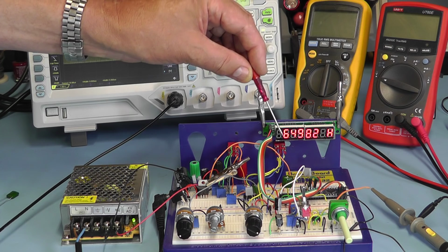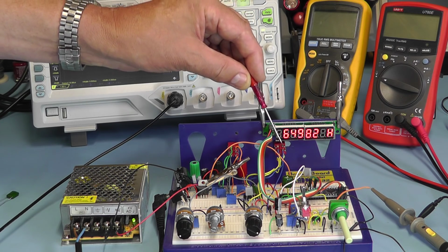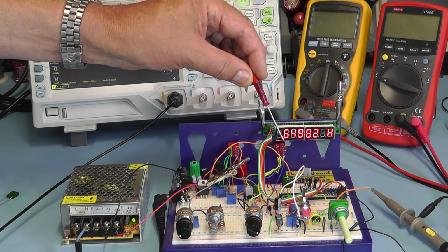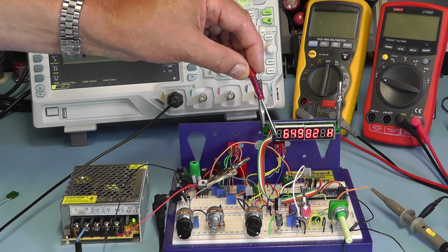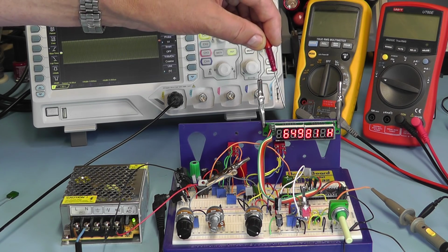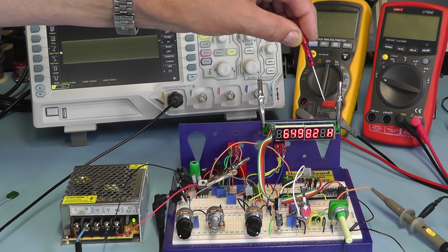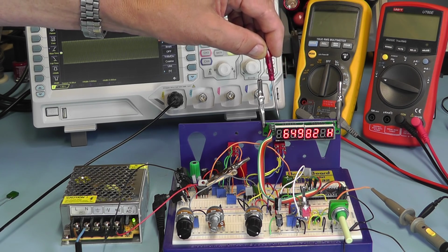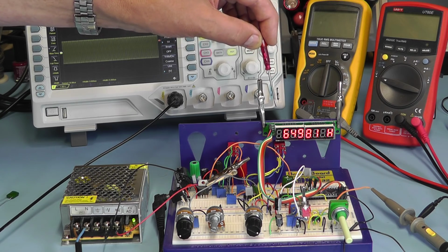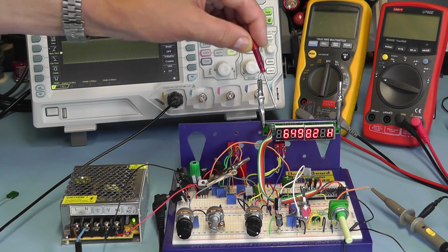I incorrectly set the data as an integer for the frequency, and that was restricting the range, so I changed that, and now I can get frequencies going much higher. In fact, I can go to in the hundreds of kilohertz if I were to change the capacitor to a much smaller value capacitor.